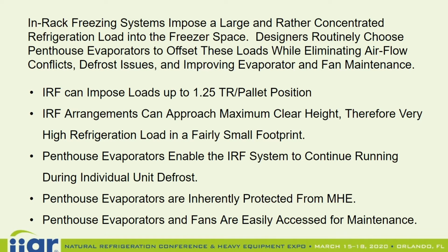It also helps eliminate potential airflow conflicts, in-room evaporator defrost issues, and all the other advantages penthouses have over in-room evaporators. Drain line routing, fan and evaporator coil maintenance all become much easier.